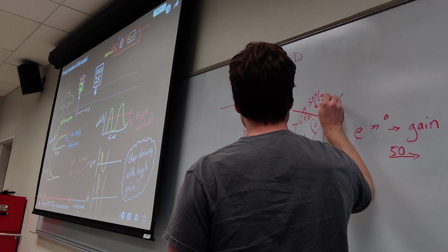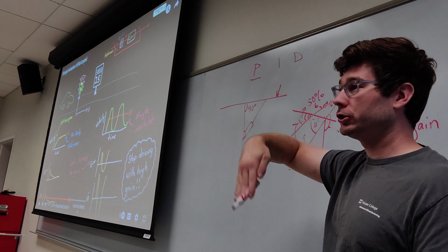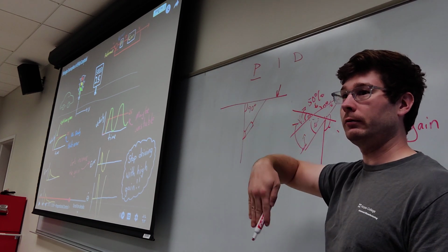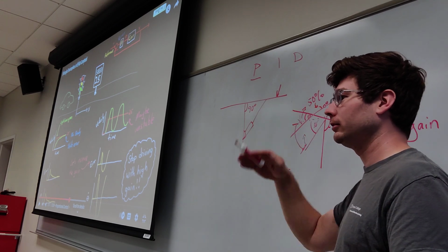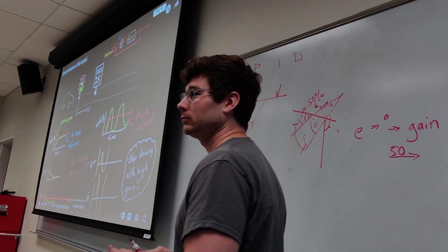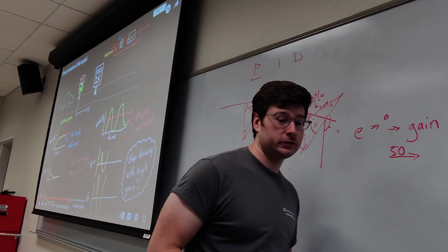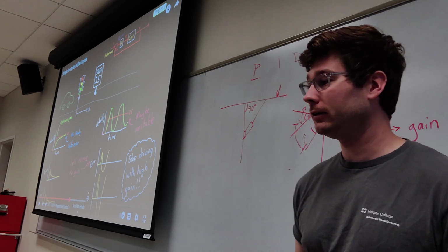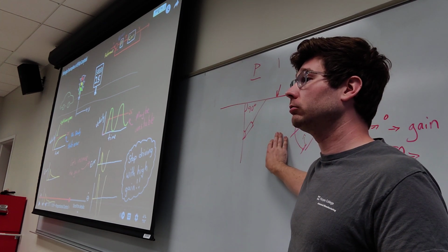It's going to swing back, and it's probably going to overshoot again. It's going to be too overzealous, and then it's going to keep chasing a target it'll never actually be able to reach. Or if it does, it'll be instantaneous, it'll be gone again, and it'll still be chasing it. It's called an oscillating system. These are the pitfalls of tuning a system and why we do PID tuning. Does this make sense so far for the P parameter and proportional control?